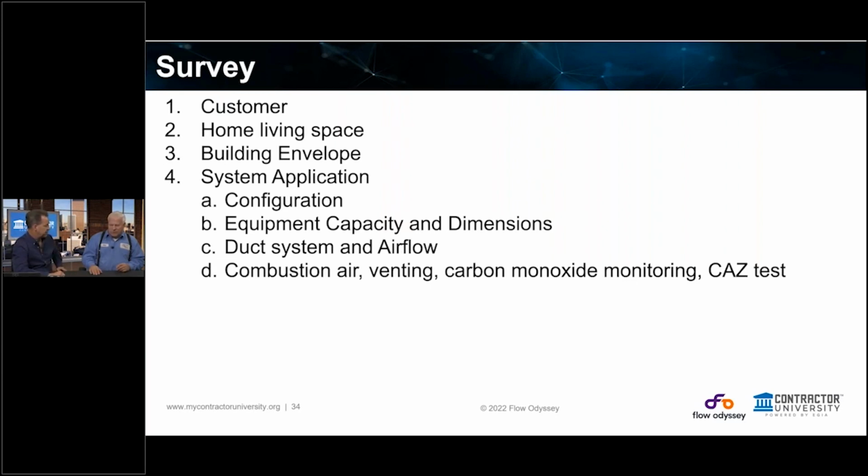Frequently, it's the same cost to put a power vent PVC fluid hot water heater in as to put a vent liner in. Yeah, and you have to realize on tank water heaters, the warranty is typically only 6 years, and so if they're beyond that, they're living on borrowed time as it is. Now, if you're at 10 years on a tank water heater, you might